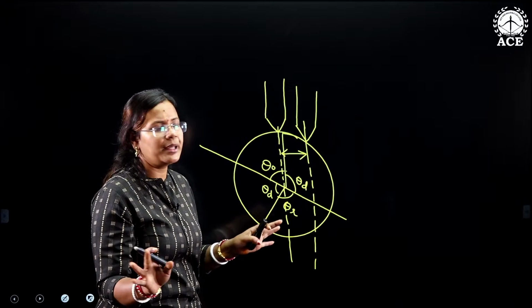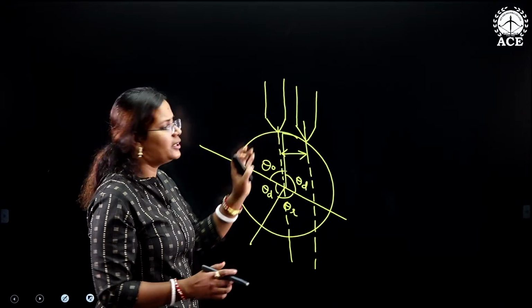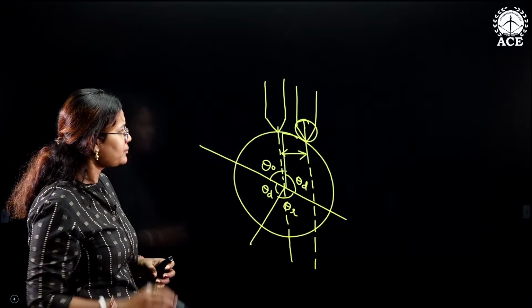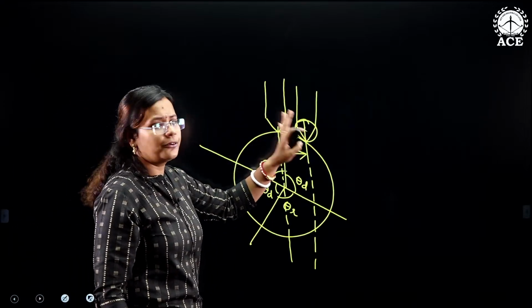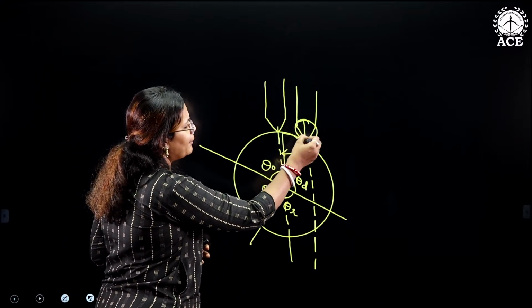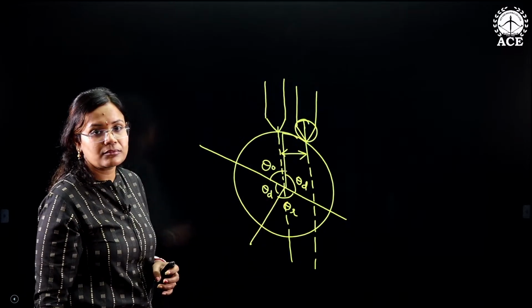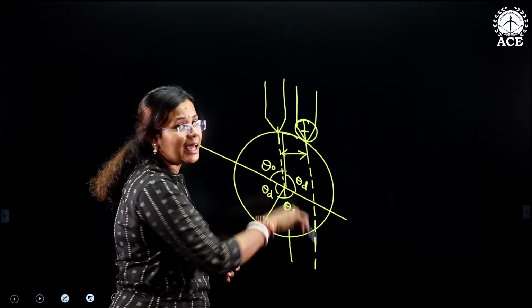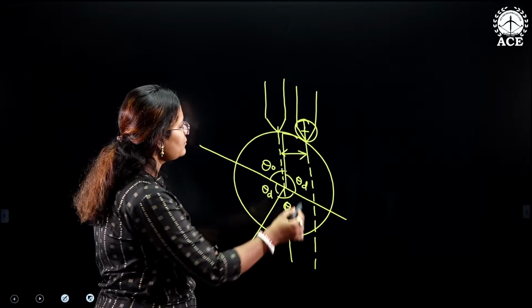The difference is that in place of the knife edge, you will draw a roller follower. For the roller follower, they will also give the diameter of the roller, and you should draw with the exact dimensions.